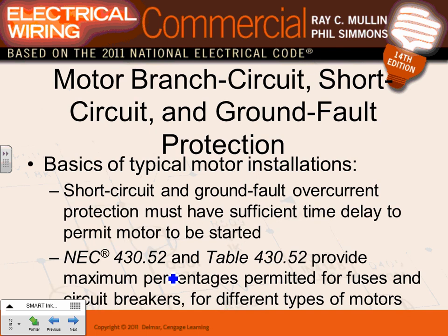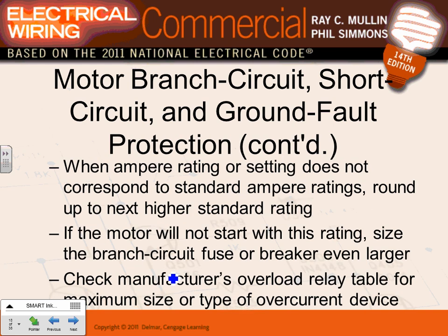We'll look at the cable in a second here. When you have short circuit protection, guys, you have to have an overcurrent protection device based on this table, which we sized many times, you and I. And that could be a dual element time delay fuse, an inverse time circuit breaker, instantaneous trip, or non-time delay fuse, sized to allow the motor to start and run. And we sized a few of these. When you do the calculation on these tables and the amp does not match a standard size, we go up, right? We've done that a few times.